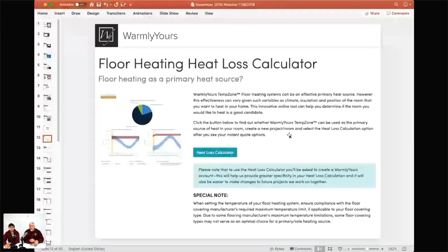of the slab between the wire and the slab, because you want the heat to go up, not into the slab. And also a good edge insulation throughout the house, depending on the whole construction factors. Right. If this were a second floor bathroom above a kitchen, we don't really care. We have enough watts in that floor, because that floor is automatically going to be like 70 degrees anyway. It doesn't take a lot of BTUs to get that floor really warm.